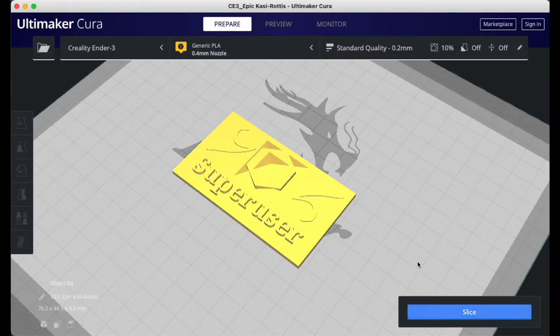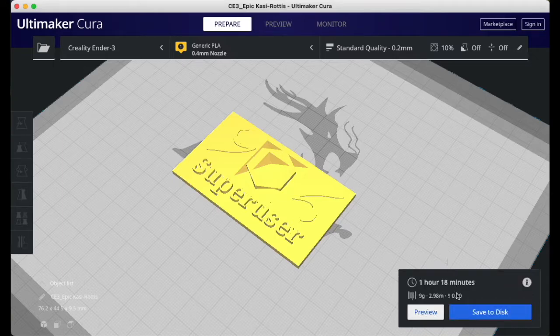So what you can do, if you are done slicing it, is plug in a micro SD card, which normally comes out of your printer, and you can plug that into your computer and do save to removable disk. So some printers need to be connected to the computer. It depends on your printer, but my printer has a micro SD card that you take out, put into the computer, you save the design on there, and then you can print it. So I will finish up and save it to my micro SD card.